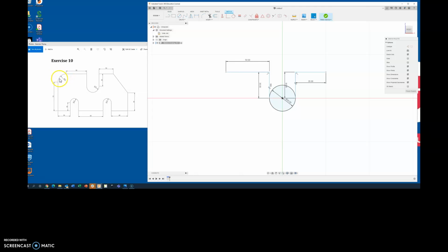And then I've got what looks like a quarter of a circle, right? When we've had half circles, we've been using that circle feature. But I don't know how to connect my circle to this line very well. So I'm going to use a different feature up here. I'm going to use a create arc, and I'm going to do a tangent arc. Okay, so my arc is tangent to this endpoint, and it's got a 20 millimeter radius. Then I'm going to pick my line tool, make sure I have them connected there, and I've got a straight line that comes down 70.